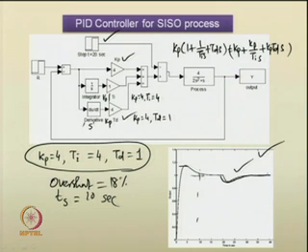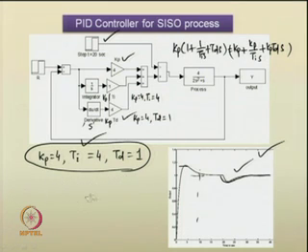So, what we have got from this, with the choice of the shown Kp, Ti, Td gains or values, the PID controller is giving us a satisfactory time response. Now, a question may arise: why did we choose Kp to be 4, Ti to be 4, or Td to be 1? Can we choose better values than those to give still better time response of the closed loop?